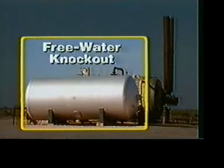A free water knockout is also a gravity-type separator. It removes excessive water from the well fluid before the fluid reaches the treating unit. Sometimes a filter or excelsior, called hay, is used to catch particles of oil that may be entrained in the free water. The free water is drained off, and only emulsion passes on to the treating unit. The free water knockout prevents overloading of the treating vessel and saves fuel.